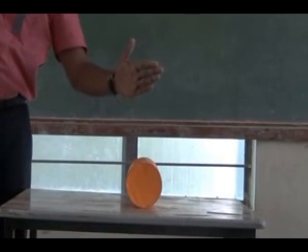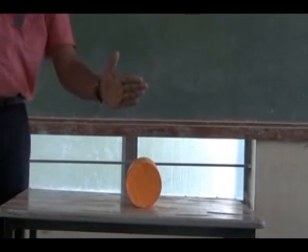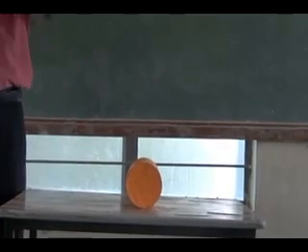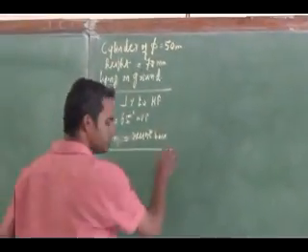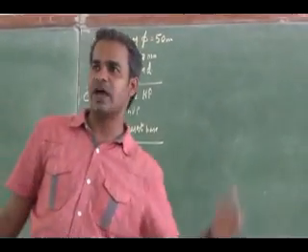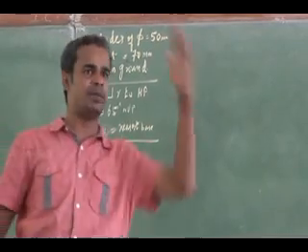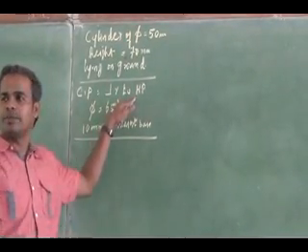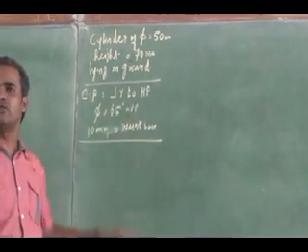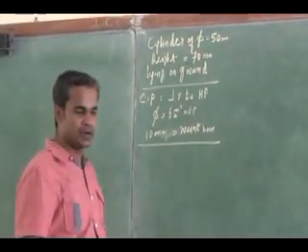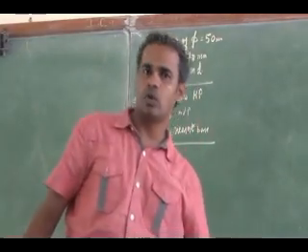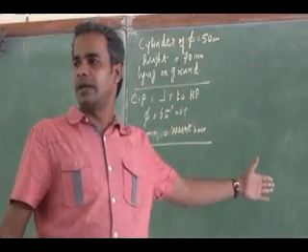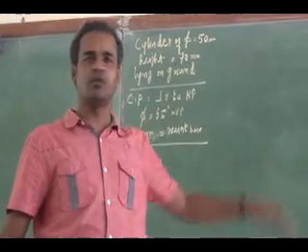Then you have to represent a cutting plane that is 65 degree inclined. So the cutting plane orientation is given. In this case, where you have to show the cutting plane, the cutting plane is perpendicular to which plane? HP. So on the top view I have to represent my cutting plane. Then what front view will I obtain? Sectional front view will be obtained.